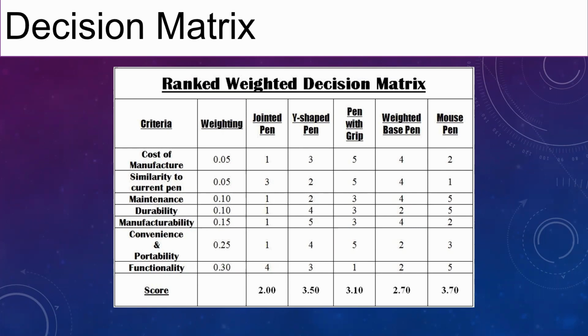Now, there are different ways you can do weighting metrics. Some people will just do a ×1, ×2, ×3. I prefer weighting each of these criteria against each other, so that your weighting should add up to 100%. Because you could say everything is really important, everything gets ×3, but weighting your criteria against each other helps you realize, where do we really need to devote the most of our focus? The goal is to get the 80% of your device done relatively quickly. That's going to get you to a prototype the fastest.